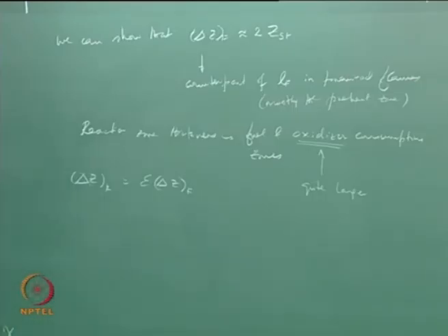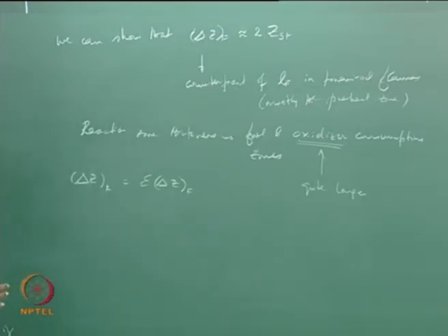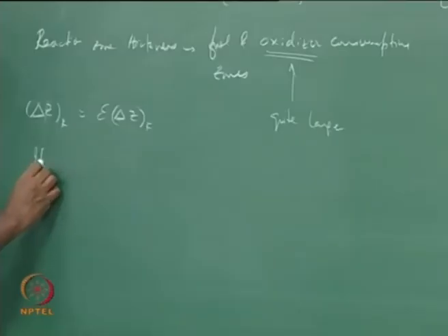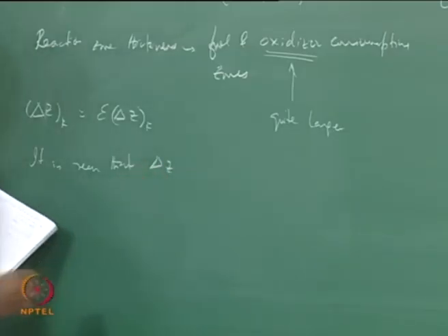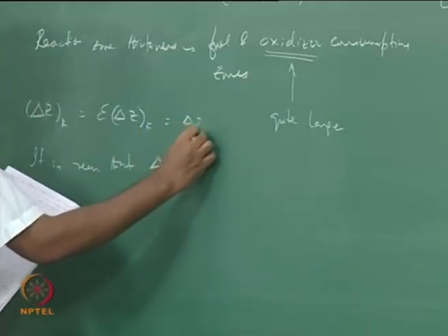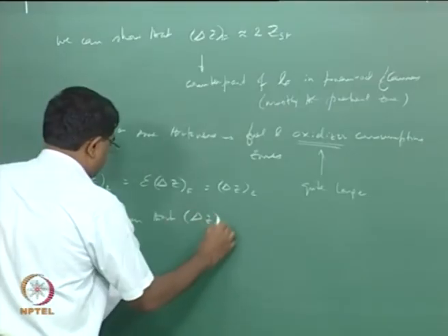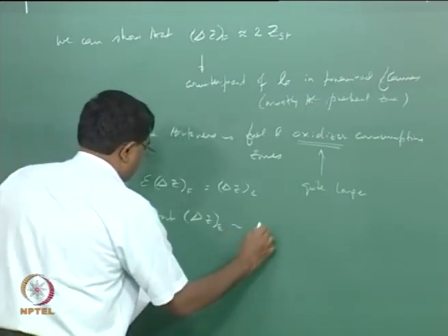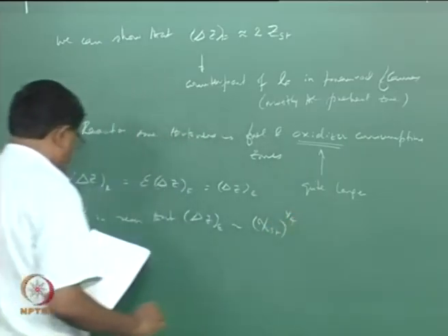Now, what we know from literature on diffusion flames with detailed kinetics, so we'll just take this empirically here, is that, let's just call what we wrote here as delta Z epsilon, delta Z epsilon goes with respect to chi st to the power 1/4.